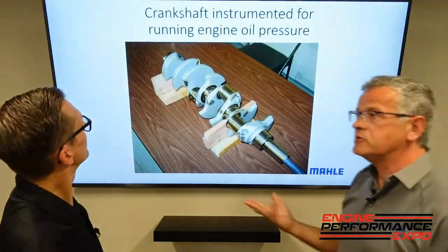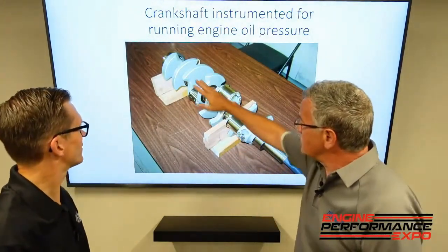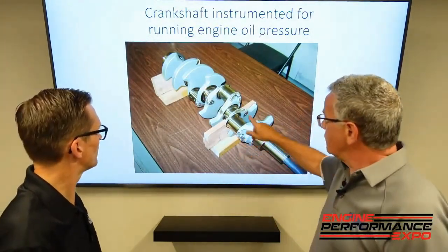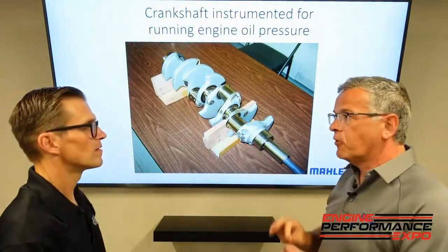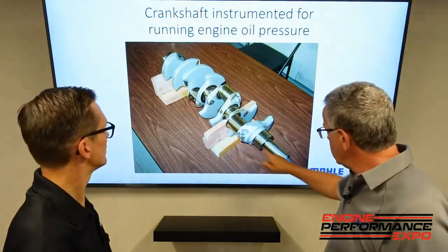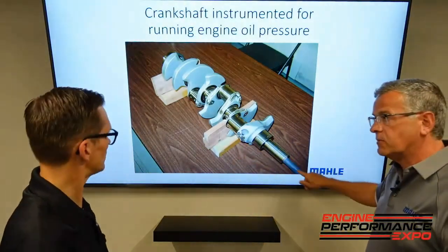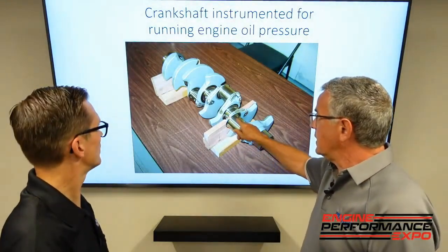Yep. Okay, so an interesting thing, I had the opportunity years ago to do some testing. So I took this crankshaft. Yep. And if you look real close, there's some instrumentation on there. Yep. Where I've actually have pressure sensors in the crankshaft as it's running. This is the wires as it's coming in there. And we measured the pressure at a main and the rod.